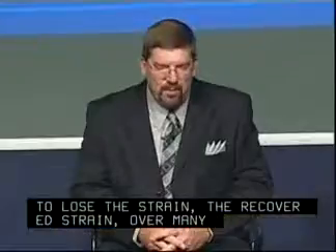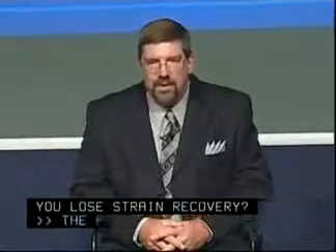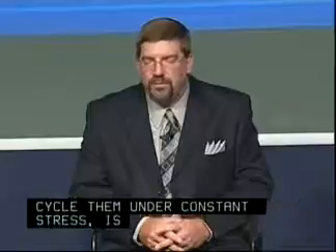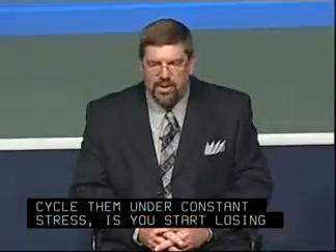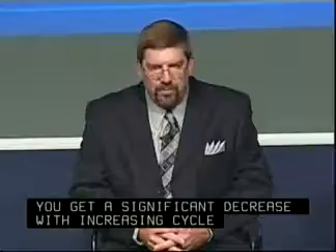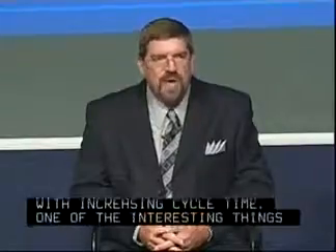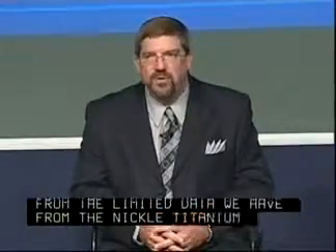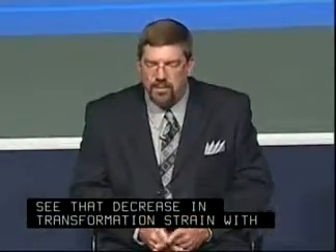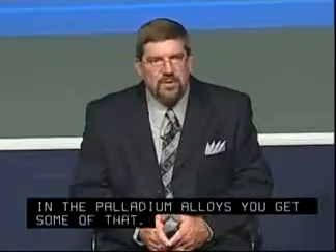All right, I understand the question now. One of the problems with shape memory alloys, especially the conventional nitinols, is that as you continually cycle them under a constant stress, you start losing transformation strain with cycling. It'll eventually, I think, plateau, but you do get a significant decrease with increasing cycle time. One of the interesting things, at least from the limited data we have from the nickel, titanium, platinum system, is that you do not see that decrease in transformation strain with cycling. In the palladium alloys, you do get some of that, but in the platinum alloys, that's another one of the advantages of the system: you do not get a degradation in transformation strain with continued cycling.